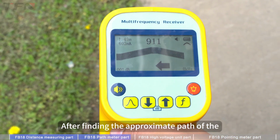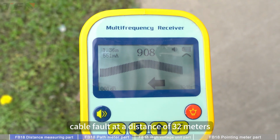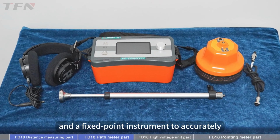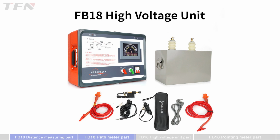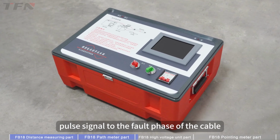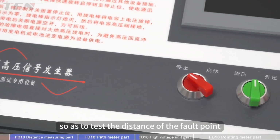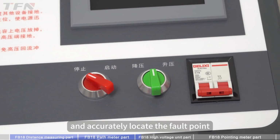After finding the approximate path of the cable fault at a distance of 32 meters, use a high-voltage signal generator and a fixed-point instrument to accurately locate the cable fault point. FB18 high-voltage unit. The function of the high-voltage signal generator is to apply a high-voltage fault signal to the fault phase of the cable. The cable fault point can generate intermittent discharge so as to test the distance of the fault point and accurately locate the fault point.